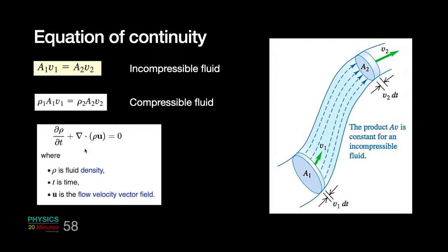So what it means is, if your fluid is diverging from the source, then the density will drop and the divergence will increase. It's more like Gauss's theorem for electrostatics, where the divergence of the electric field is related to the amount of charge present in the given volume. So you have done that Maxwell's law, more or less a similar concept. Now, if your density is constant, then this becomes 0. That brings del dot u to be equal to 0. And if you work out from here also, you can derive this equation.